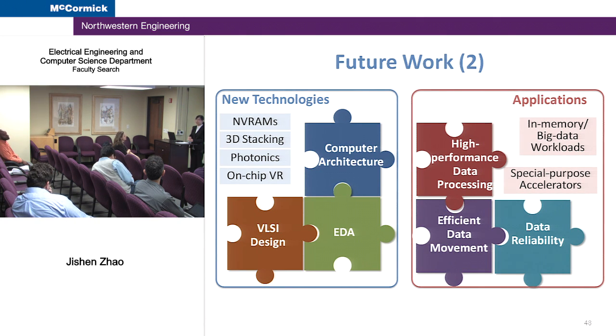A lot of people talk about phase change memory because it has been closer to production in recent years. But I see STT-RAM coming up maybe last year, like the Everspin company I mentioned. And for ReRAM, I know that in China and Taiwan, I cannot remember the company, they shipped demos, but ReRAM is maybe a little less close to the market than phase change memory.